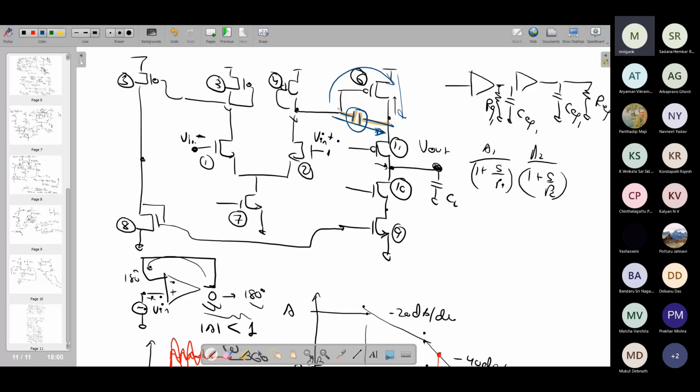When you have an additional feed forward path inserted in the circuit, it leads to stronger zeros that we need to address in the response. For the time being, in this circuit, you don't have such a significant zero. We will look at the zero case in one of our following configurations.